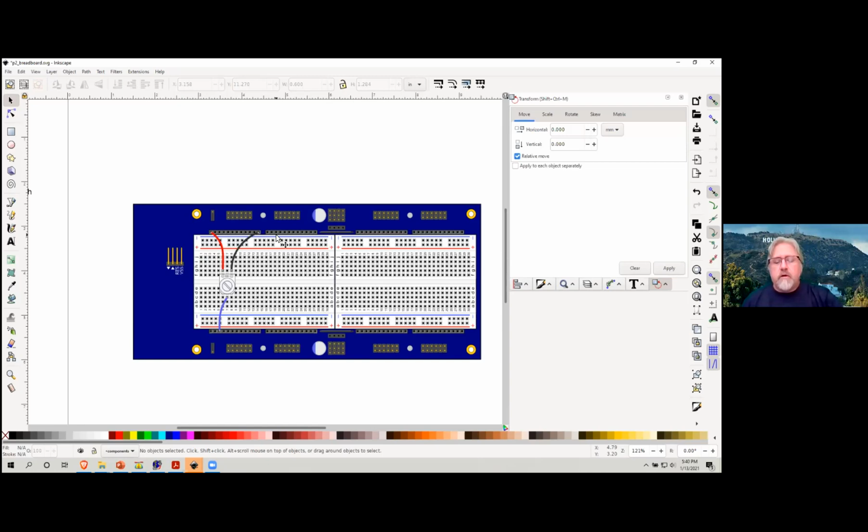The great thing about, even if you use just the C program, is that if you use Spin as a test environment, you can test a bit of assembly really easily and then move it over into C. Yeah, well, you can do the inline assembly in the C code and test. Oh, yeah, technically you can. It's really similar to the Spin inline assembly. Yeah. It's just compiling it as hub exec instead of native cog code. Although you can do native cog code with other decorations and advanced settings, but.